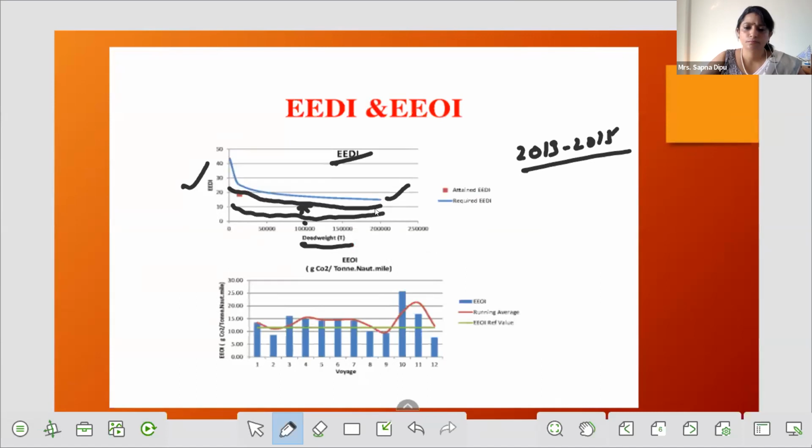So a young naval architect now, whoever is in the design sector, when designing after 2020 or after 2025, has to check in which EEDI phase the vessel is coming, and accordingly his EEDI value should meet that requirement. But in fact, phase 3 has been brought forward. Now we are already in phase 3 from 2022 onwards. This is as far as EEDI is concerned. Same with EEXI for existing ships, the formulation and all is the same.